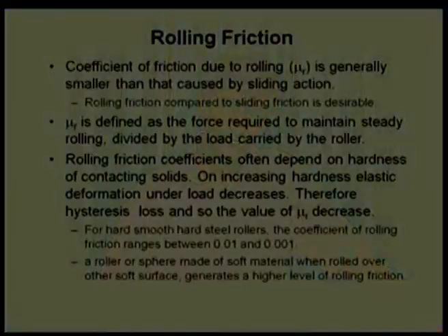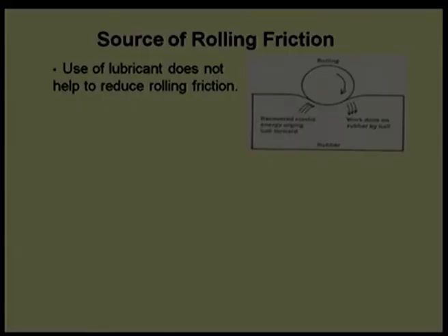So, 4 mechanisms, but we are assuming for timing that we are not going into the plastic domain. The plastic domain coefficient of friction is neglected in this case, and there is a very low chance of micro slip, very low chance of excessive heating. So, we will consider only the elastic case. Suppose elastic itself is going to give a coefficient of friction.